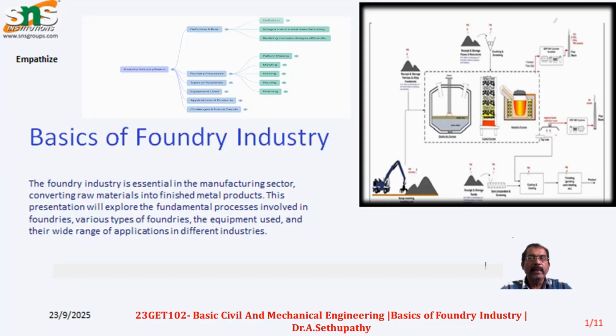These are binding agents mixed with the silica sand, placed on the pattern covered by the boxes, rammed, and then the runner and riser are fixed. The runner is used for pouring the molten metal inside the mold cavity. The riser is used so that after filling the cavity, the material comes out through the riser holes. Some other air vent holes are also made in the top box of the mold.